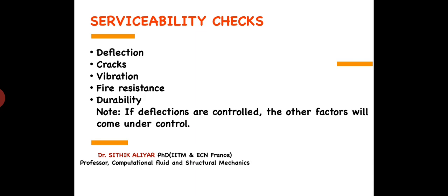For very peculiar structures, even port and harbor structures, we do crack width checks for the pile foundation, because most of the portion of the pile above the seabed is exposed to seawater. The seawater keeps coming and splashing the pile. So when there is a crack, even a very small one, the water can penetrate inside and corrode the reinforcement. The crack width check is another serviceability check which is not concerned with your strength. Whatever the bending moment, shear force or torsion, anything can happen, but the crack width will change the total design.